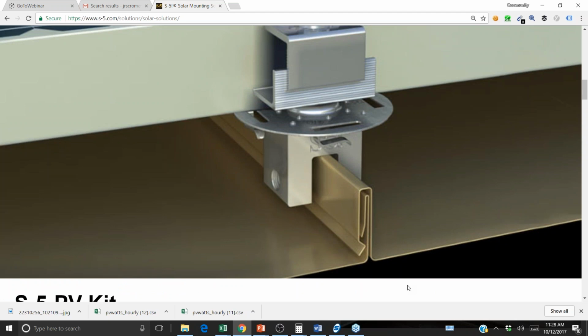Well, what about the cables that come out of the solar array? If you don't go into the roof, then you have to go across the roof. And I think running your solar cables across the roof looks bad. Not always, but I like to hide my combiner boxes and stuff underneath the array and go into the roof deck rather than across the roof.